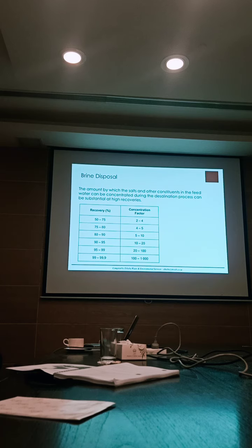Is it possible to run 100 to 1000 cycles of concentration? That's not the cycle, that's the concentration factor. So your recovery there is 99%. So you're really pushing it. Is it possible for seawater? Yes, you can do it in stages. So that will be a cumulative effect.